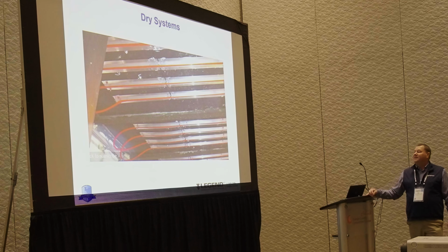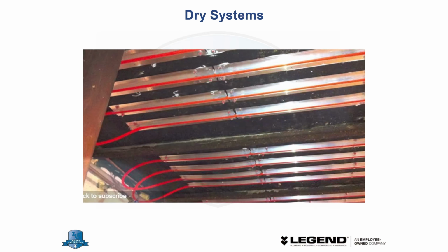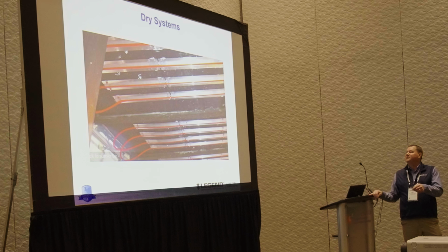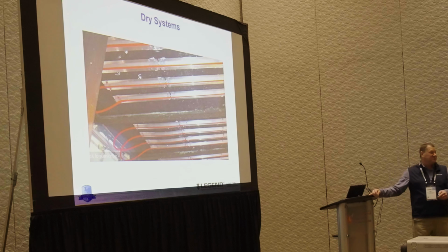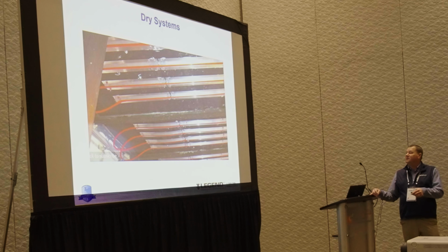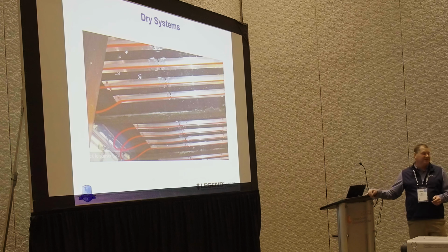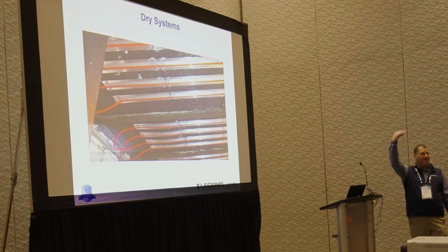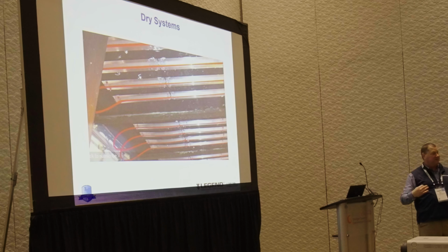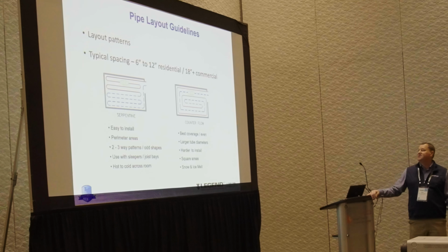180-degree water through that. Yeah. Heat transfer plates, these are fine, but this project is actually a porch. This is a vault below a porch. They were trying to stone out the porch above it. They stapled the heat transfer plates, or not stapled them, they actually used like a Remington shotgun, got them all up in there. Did a great job here, left this nice and loose, because that's what they're supposed to do, allow for that. But I don't know what the transfer is through 4 inches of concrete into the porch. It might melt snow, it might not, but probably not. But the area below there could be warm. But anyway, even if they did that all, you've got to insulate below that, because the R value of that cement is much higher than no R value below. So making sure you're insulating below a situation like this is always important.